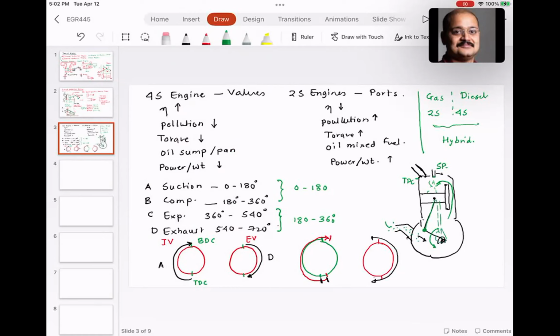So there was no articulation, which made the engine super compact. That is called the hypocycloid engine. So if you Google, we wrote a couple of papers on design of the Weissman hypocycloid engine, where the connecting rod and crankshaft are made up of one solid piece.